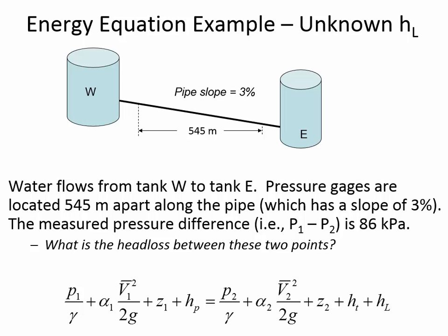As the water is flowing through the pipe, that resistance that the pipe is imparting to the flowing fluid steals pressure. When you lose energy, the energy can be lost in 3 places. You can lose energy as velocity, as elevation, or as pressure.